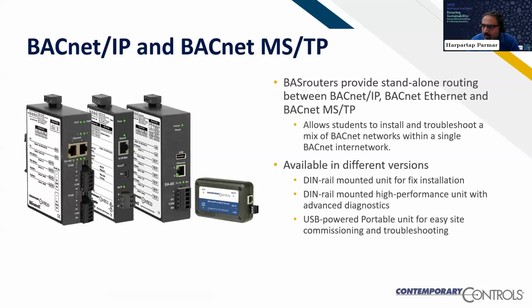Moving on, you may also need the ability to interconnect BACnet MSTP and IP devices. Even though people are moving towards BACnet IP networks, BACnet MSTP is still very prevalent in the industry. So it is imperative the students know about BACnet IP and MSTP, and they may need to connect those two networks together. We do have BACnet routers to connect BACnet IP and MSTP, and it gives another option for students to learn what's common in the industry and in building automation networks.